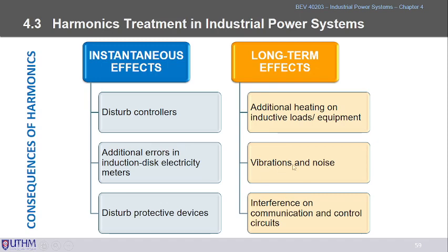And of course, with the variations of the sinusoidal waveform from the 50 hertz, you can count the harmonic content. That means with harmonic content in the waveforms, it will have vibration and noise, especially audible noise when you're operating the induction motor with harmonic content. Your voltage and current have been disturbed by the harmonics, and it is no more a pure sinusoidal waveform.